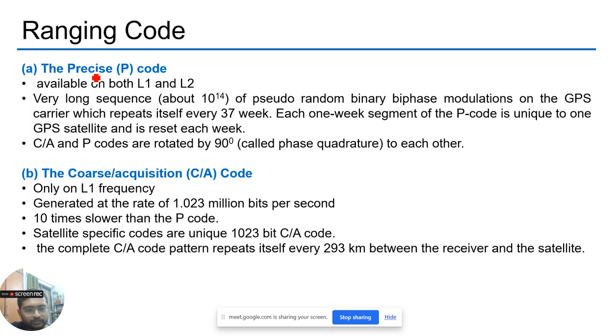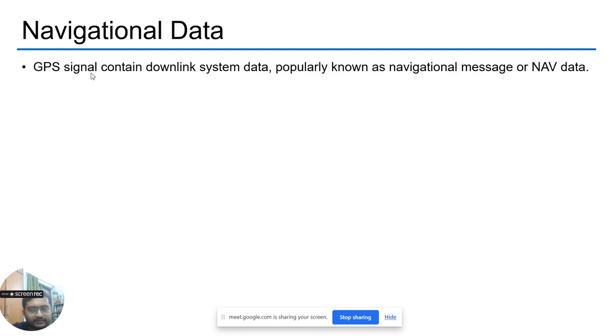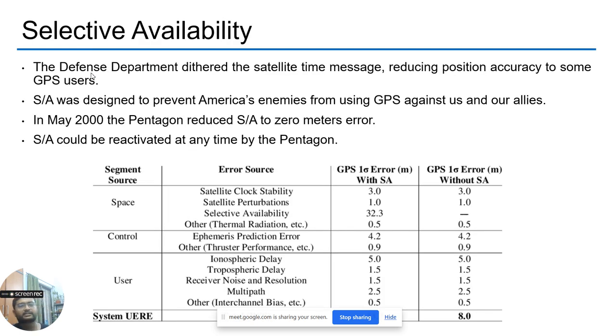Okay. So just keep in mind at what wavelength it operates and what frequency it has. It will help you identify how it will affect the signals and errors. Then we have different terms you should know, such as integer ambiguity, cycle slip, selective availability. Selective availability is like this: earlier these signals were used for defense purposes only, so it would introduce error into the signal. After 2000, they removed this selective availability, and after removing it, we are getting a little bit higher accuracy.